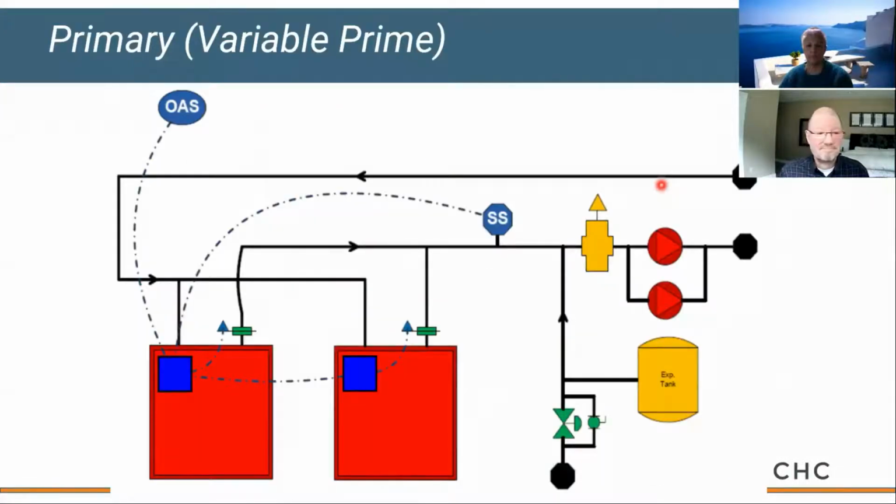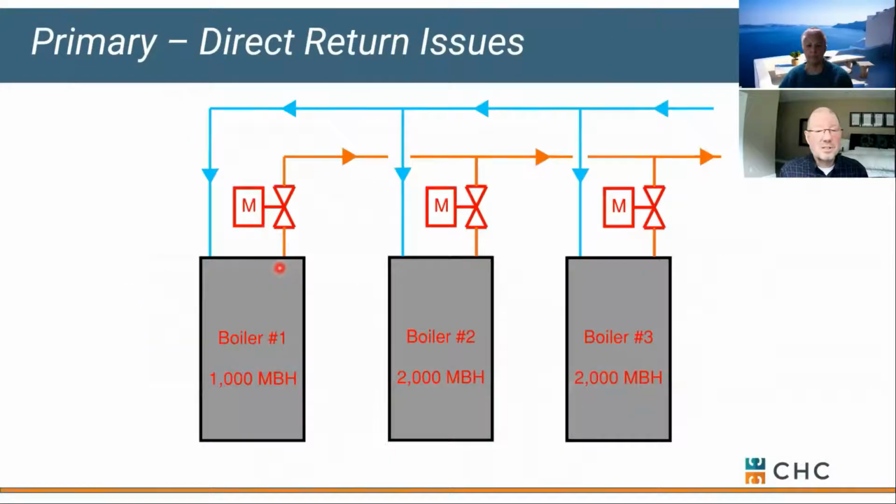Okay. Another good example of reverse return. First boiler served with cold water is the one on the left. Here's a motorized valve. Okay, and it's the last one returned prior to our system pumps. So good indication of reverse return piping. Now that's going to be important in water heaters too, right? But also with boilers set up for primary only.